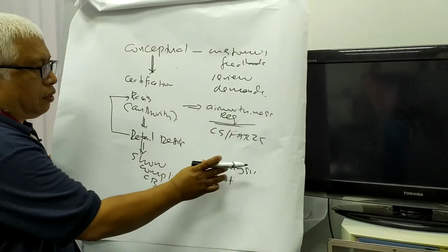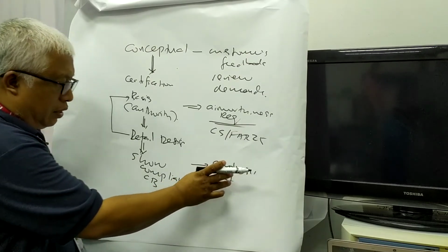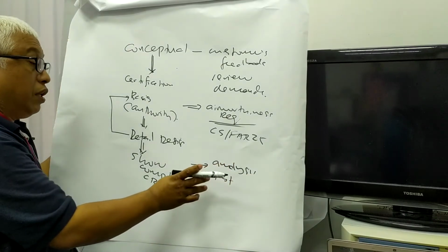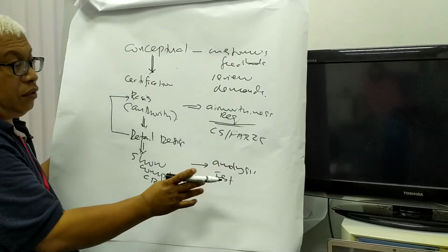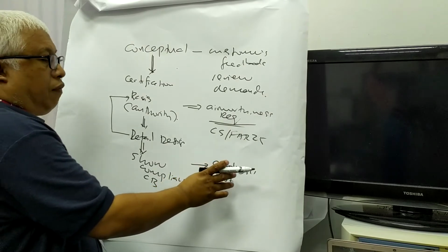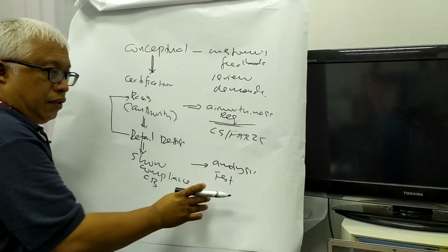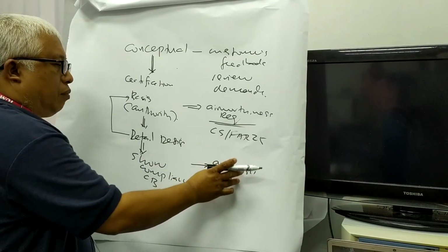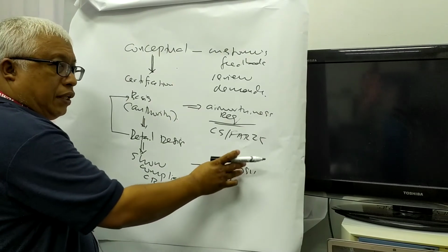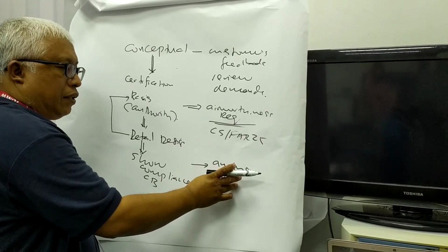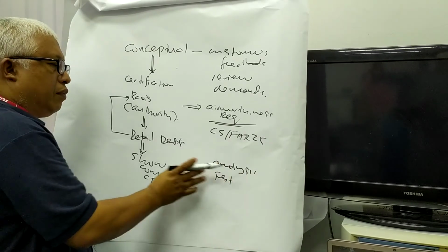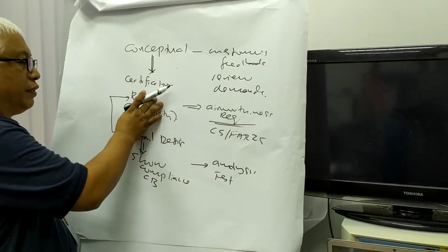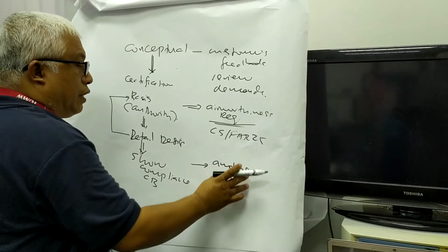So here we are maybe talking about stress analysis, engine performance analysis, engine performance test, landing distance, takeoff distance. So this is analysis and test. Normally they come coupled together, analysis validated by the test, so you will not end up testing everything. So this is the process. During the process of showing compliance to the certification basis, we have the process of analysis and test.